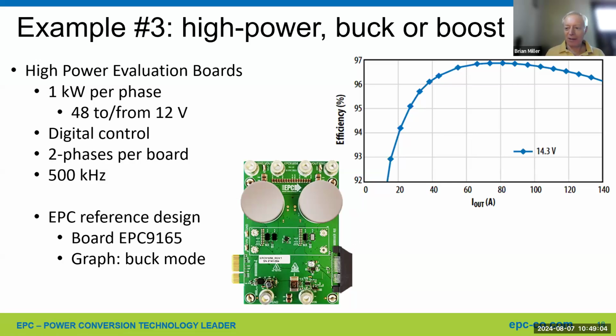You mentioned something else? EMI. EMI, yeah. Well, I guess it helps that you can ground the heat sink if you'd like, because you need electrical insulation anyway for a top FET and bottom FET. So that's possible. So you can kind of encase it there. So having that, plus having some inner layers of the board.